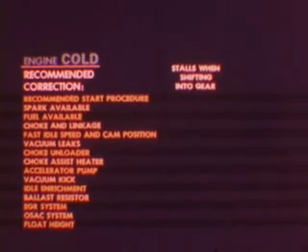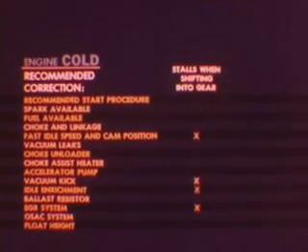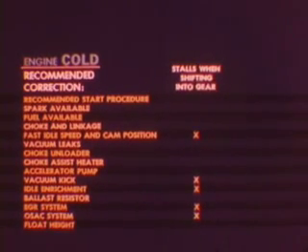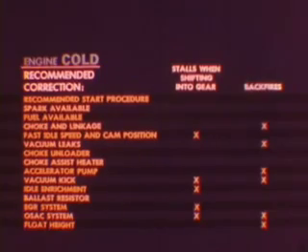Here we are concerned with correct vacuum kick, fast idle speed, and cam position. The EGR valve may leak or open too soon. Idle enrichment shuts down too early, or the OSAC system does not work properly. Usually, if a cold engine backfires, we can suspect a lean mixture or late spark or valve timing. We've already discussed the most frequent causes of lean mixtures, so we'll only indicate the pertinent ones here.